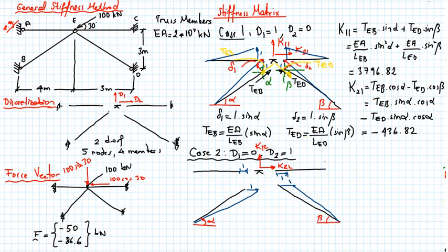What I need to do is to calculate this, the transverse component of the translation, and this is the translation along the member's direction. So for me, this is delta 1, the translation along the member axis, and the translation along the transverse direction is delta 2.